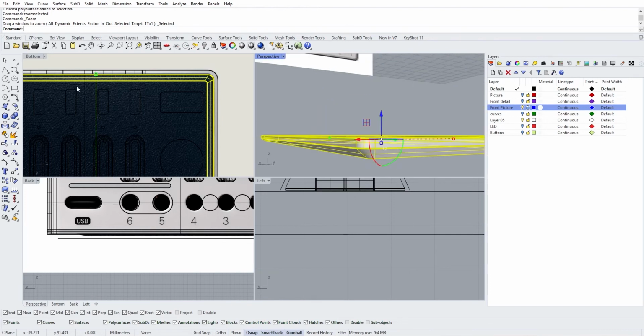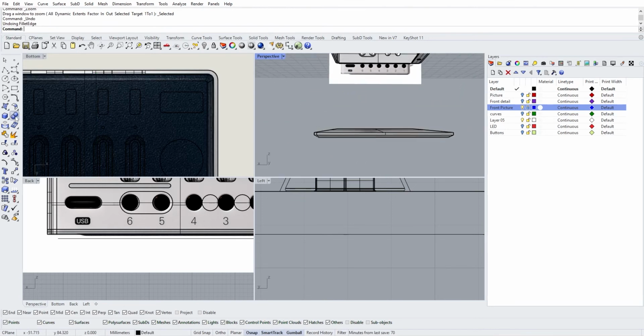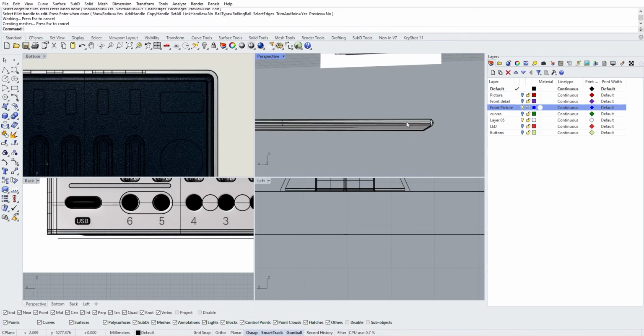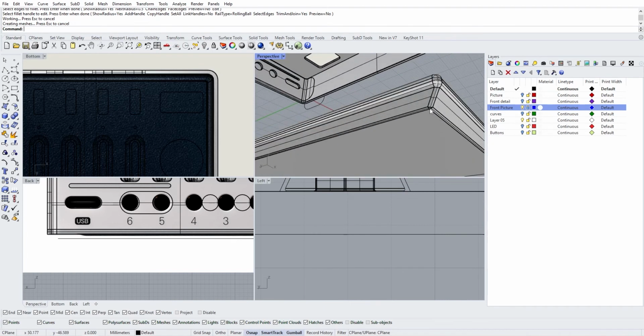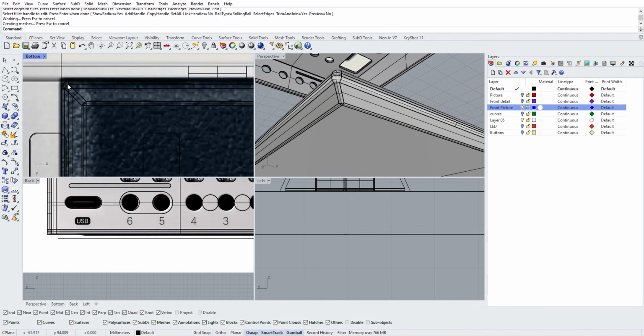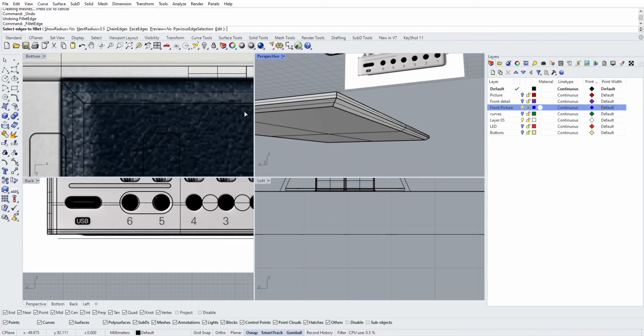It's supposed to be something which is a bit not as hard because it's fabric. I mean, it's leather, so maybe we can add a fillet which is a bit bigger. So instead of 0.1, let's try 0.5, like this. Maybe it's a bit too much. Let's come back to, let's try 0.2 here.